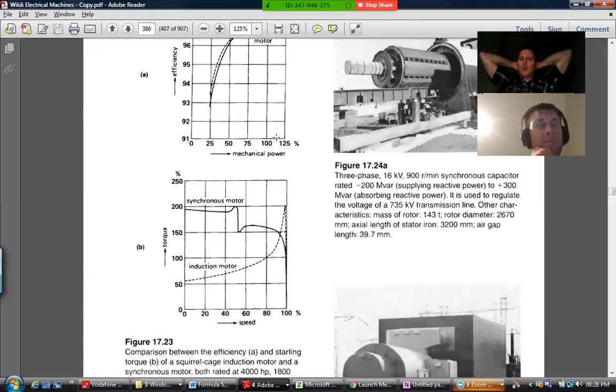Now, in the motor scenario, there's normally only one scenario because effectively it's always grid connected. You're supplying it from the grid. So there's only one phasor diagram for the motor, not like the generator where you could have an isolated load or the infinite bus. So that's a separate question for the motor. Also, it just revolves around those phasor diagrams. And that's all we need for that 3rd assignment.